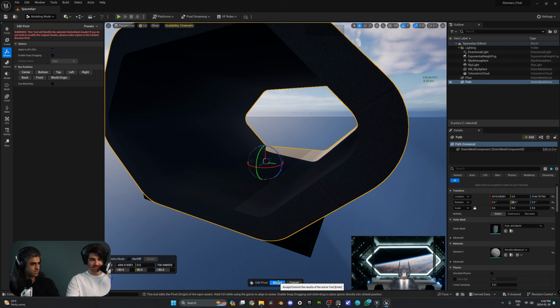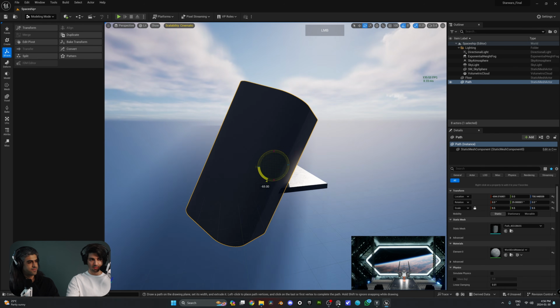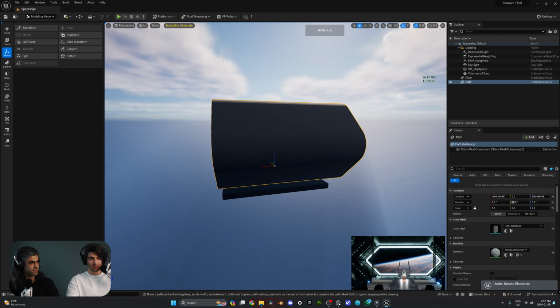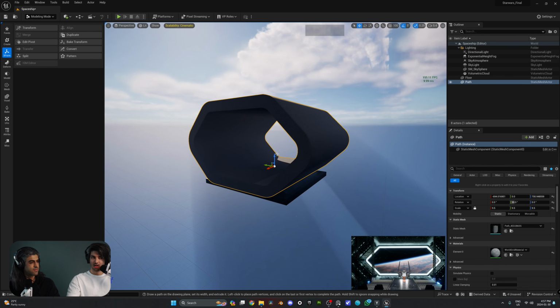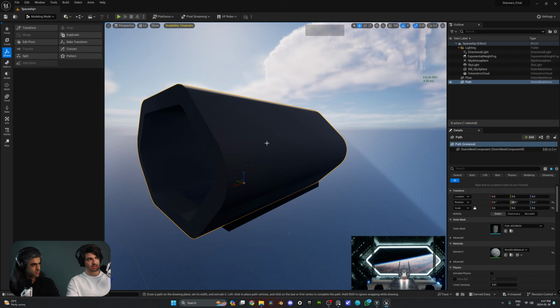If I go ahead and hit accept, right, the origin is now changed. So if I were to rotate, it's rotating from the bottom middle part. And if I were to reset the location of my hangar, look at what happens. It comes to the precise world origin, the 0, 0, 0 of my X, Y, and Z. And that's what I usually like to do with my models. And plus, we wanted to look for an excuse to teach you guys how to edit your pivot points.